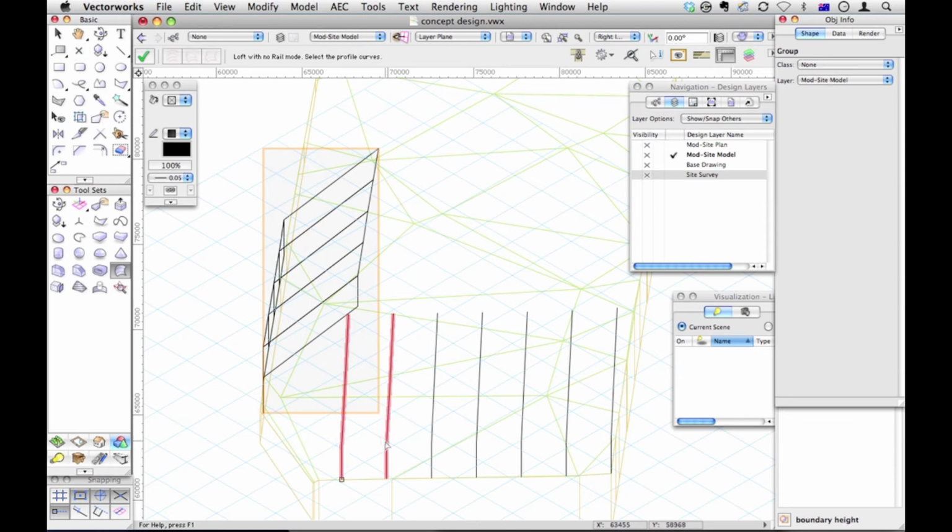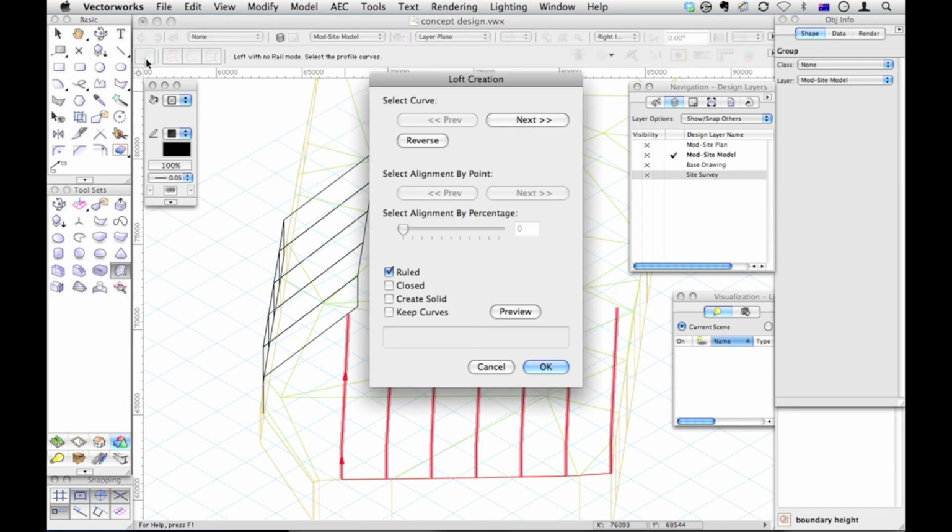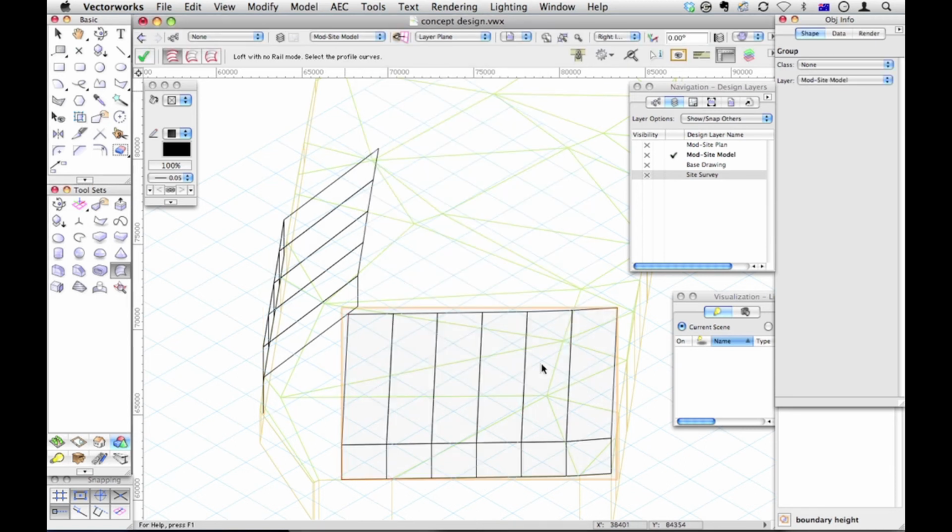So there, there, there. Now as long as you're clicking at the same end of the NURBS curves, that would be a problem if I did that. But if I click at the bottom edge, that's fine, or at the top edge, that's fine. So let's create that into a recession plane as well. So now what I should have is a recession plane where I can look at my building and see whether my single story building goes through this recession plane.